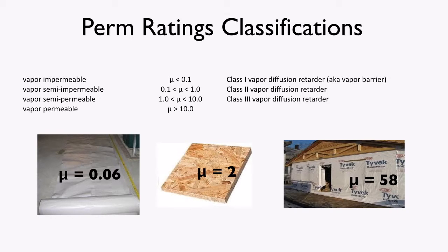If you live in a hot, humid climate, or if you have internal sources of moisture which are not being actively controlled, then you should certainly be very cautious about putting an insulative material or a vapor barrier in any of your assemblies. So basically, don't do it unless you know what you're doing.